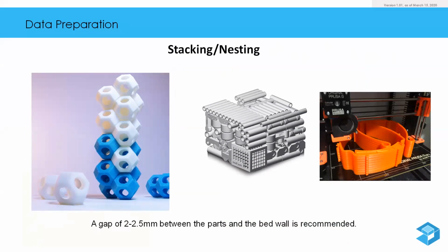Now, in data preparation, another thing that happens is that when you have multiple components, say 10 components together, you will not print one component at a time. You'd want to stack them together. Stacking as in, let's take, for example, this 3D octagonal structure over here, hexagonal structure.